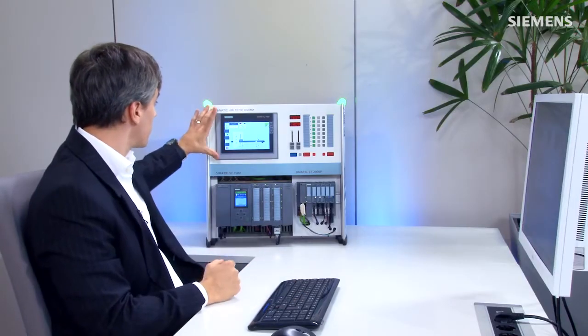Remote HMI access can be a huge benefit for any engineer because you can quickly and efficiently get diagnostics with a web browser, and you can build more elegant HMI architectures with a control icon from our libraries. Let me show you how easy they can be. As you can see, here is the comfort panel we actually want to enable the remote access for.